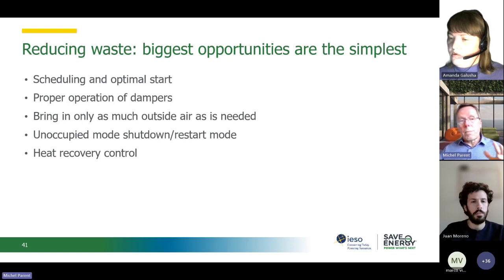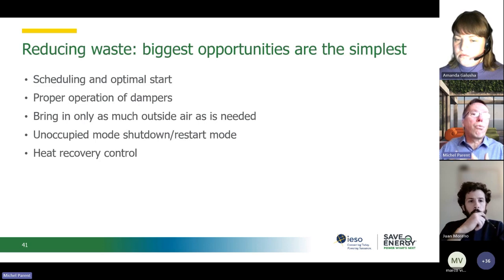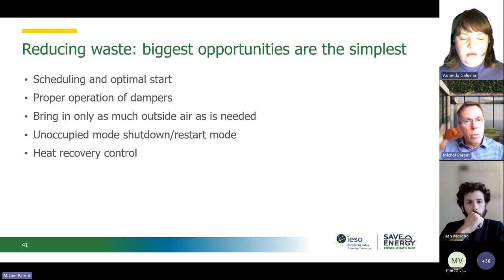And heat recovery, too many times I've seen heat recovery devices installed but not running properly. No diagnostic done on their heat recovery. So you want to reduce the load, another saving mechanism, by using your heat recovery properly. It's easy to diagnose a heat recovery device. You look at the delta T on one side, look at the delta T on the other side of your heat recovery device.